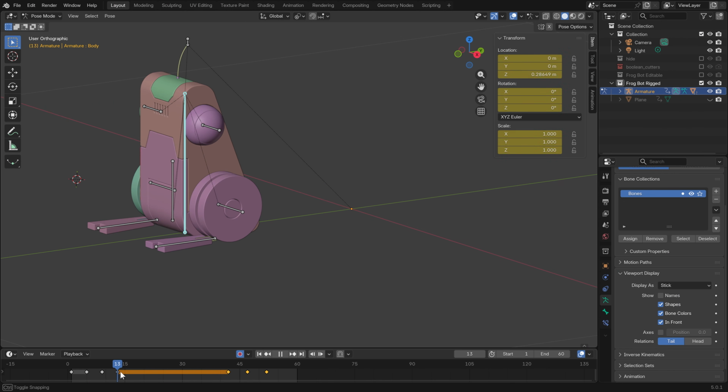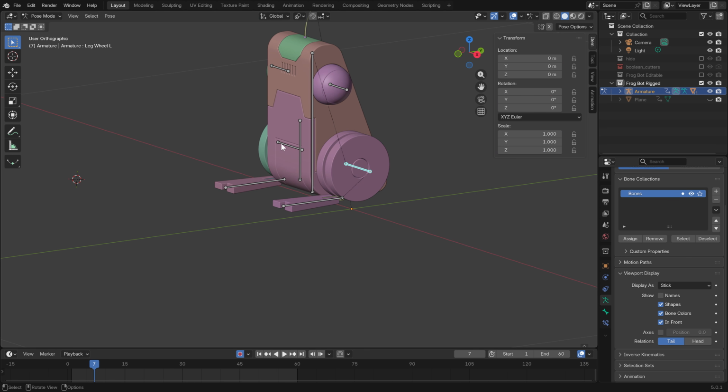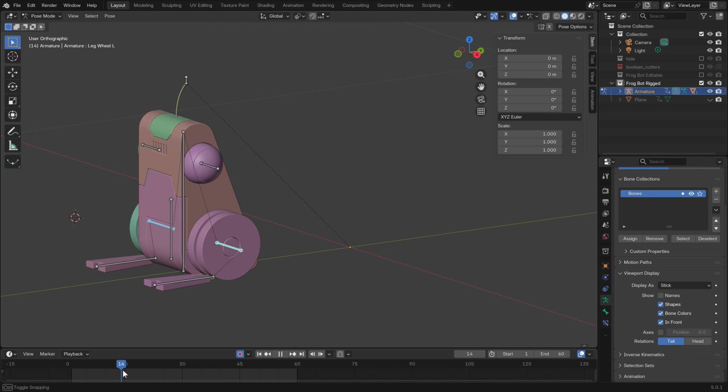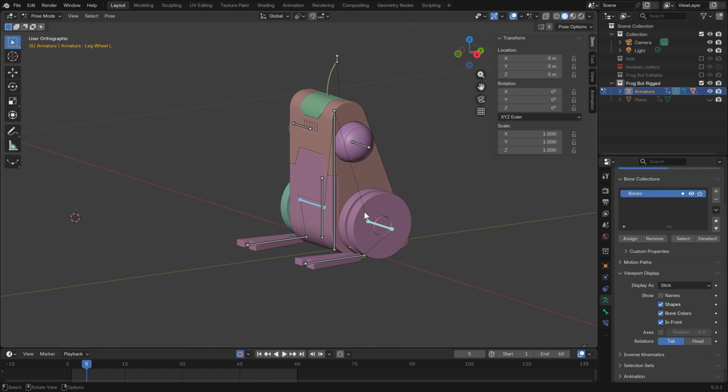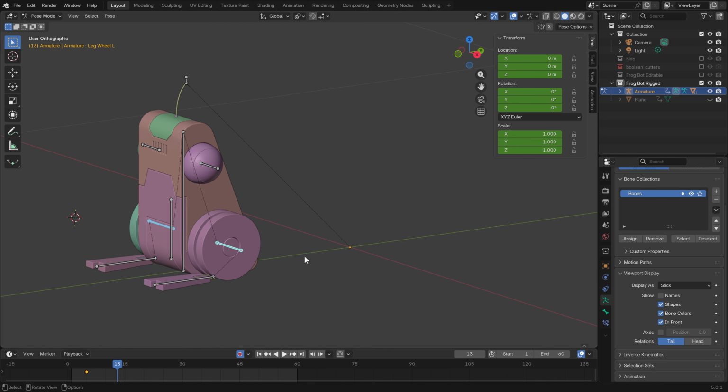Okay, we have our body animation done, but we want to motivate it with the spinning of our legs here. So we can select both of our leg bones by shift and left clicking. And then as we know, the animation starts at frame 5. We can hit I over the 3D viewport to commit our first set of keyframes. And then we land at frame 13.